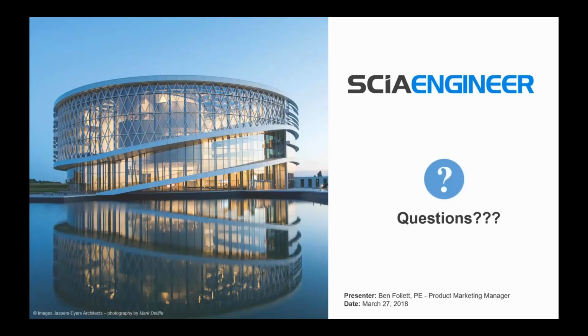Someone asked, can a steel floor be modeled to sit on top of the concrete mat? Sure. It's just a matter of modeling, whether you want to model it as a steel floor with the two kind of integrated into each other. We would use something called a subregion, basically to say, I have a 12-inch slab, but the top 2 inches or the top 1 inch or whatever is a steel plate, and maybe it's a steel plate over the entire thing, or maybe it's just a steel plate in the portion of the tank. We could do that, no problem. The software would understand that we have a variable material, which would give us variable stresses and variable deflections. It would understand that when we use a subregion.